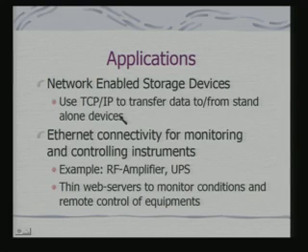So, these storage devices become standalone devices if they become TCP IP enabled. So, use TCP IP to transfer data to and fro from standalone devices. So, this protocol gets implemented. I have already shown a module for implementation of Ethernet. On that similar module, you can have the complete TCP IP implemented, and you attach that to hard disk hardware, you effectively get a networked storage system.